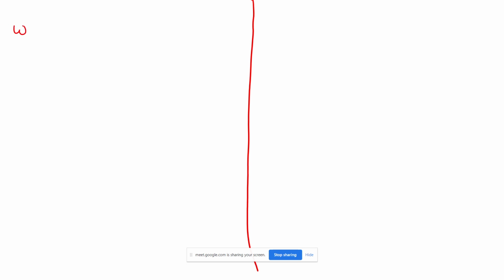We can write work actual of turbine is equal to eta T into Cp into T3 (1 minus 1 upon Rp to the power (gamma minus 1) upon gamma).